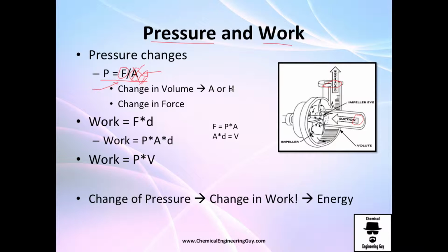If we change the volume, that is the area or the height of something, we're going to have a differential of displacement. So for example, force times displacement is equal to work. Okay, so we have this definition I told you. Instead of having F, which is force, let's make it pressure. So we need to have pressure times area. We have it right here, and we have distance right here. Recall that area times distance of displacement or height will give you a volume. So we have this definition of work.